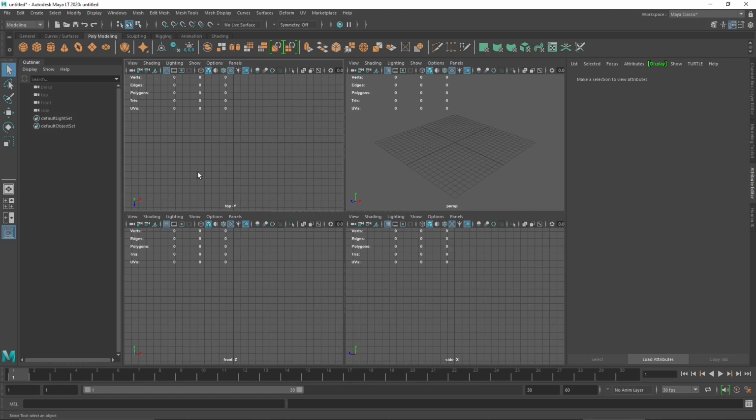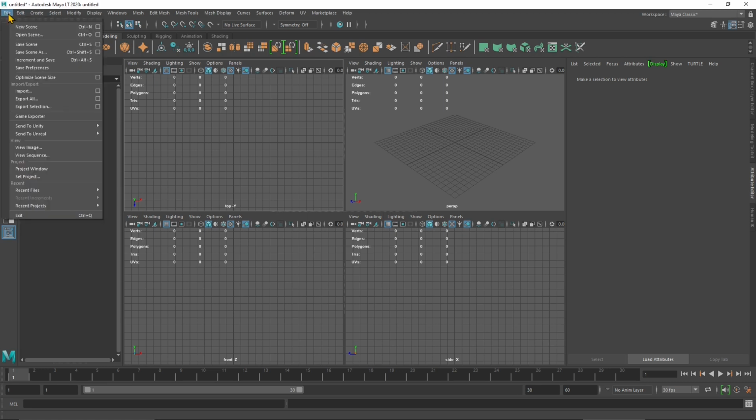In this video, we will continue to talk about basic commands in Maya, and we are going to also start to work a little bit with more precision. We're gonna use some of the preferences to set up our software and interface. We're going to use some units, and we will see how we can set up units. So I'm gonna start here by opening up the recent files.